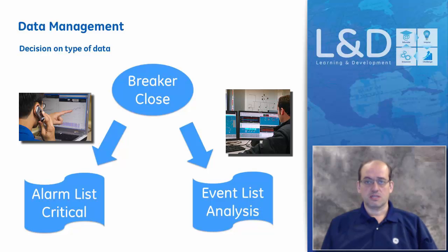For example, if a relay is giving 50 points or 50 alarms, maybe the operator at the central management system does not want to take a look at all 50 alarms, and all that's required is to OR all of the 50 alarms into a single alarm, and that single alarm will go back to the central management system, which indicates whether there is an immediate requirement or a remote requirement for a person to come to a substation to service the alarm.